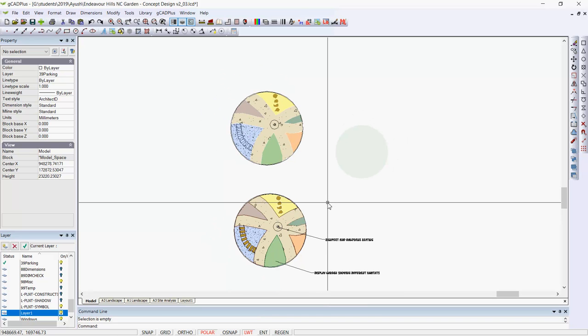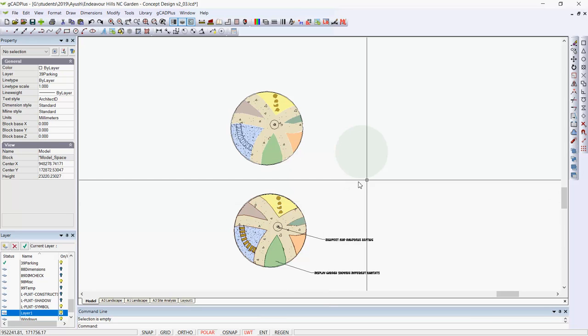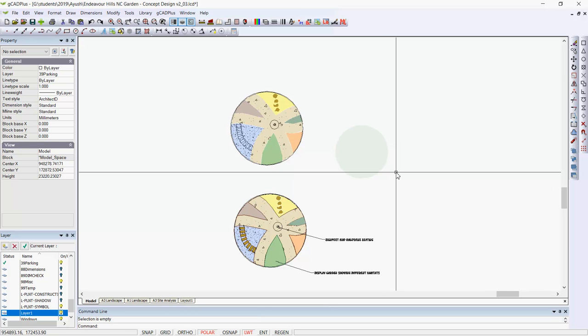Now once that's done, you can print the drawing using a high quality PDF writer, and you get very high resolution. So what I'm going to do now is remove all references to transparency and then print the same drawing we printed before, and we'll get a much higher resolution.